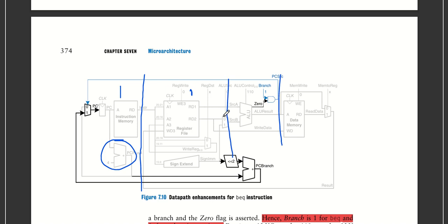We don't need different ALUs, one adder here and another adder here. It's a waste of hardware. But if it was multi-cycle, we could use the same hardware for different cycles, because one cycle might not use it, so the previous cycle can use the hardware and the next cycle can use it when it is free. We will see the differences, but that's one major advantage of the multi-cycle data path over the single cycle.